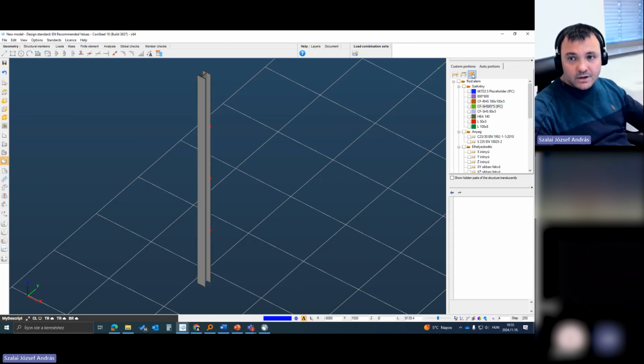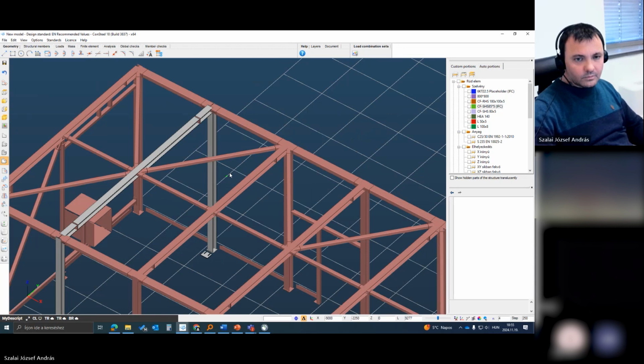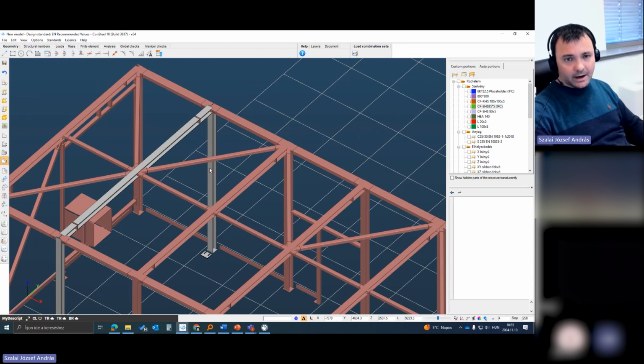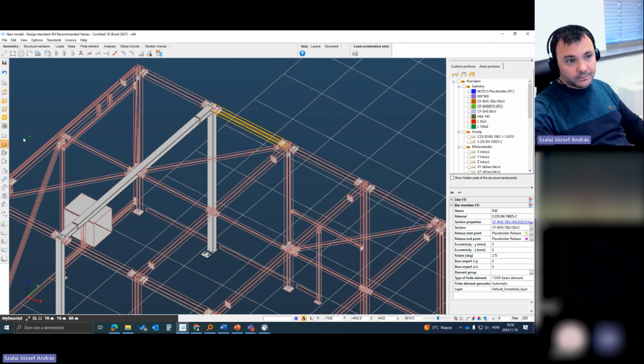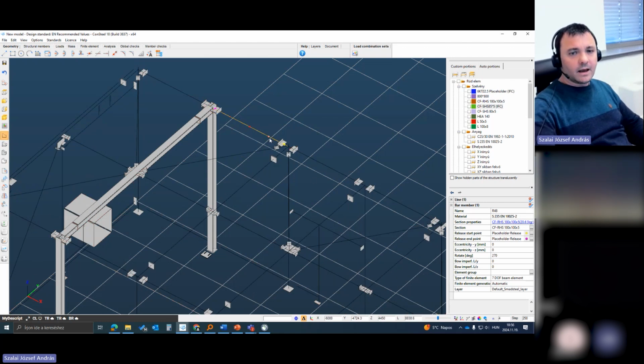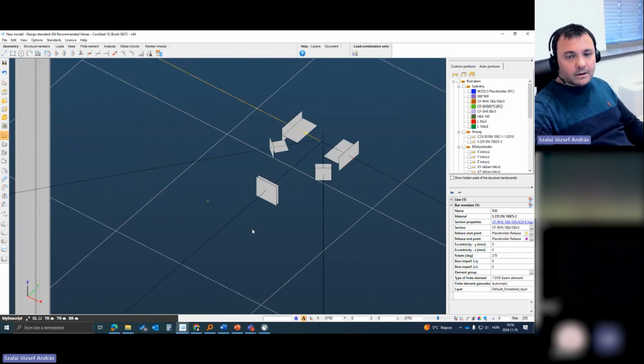The other representation type, object or beam member representation, is the extruded area, and all the others are that type. So in this type of IFC export, we have the reference line, like in Consteel here, and on the reference line we have the cross-section for which we can use the cross-section conversion, and that creates a complete structural member in Consteel.